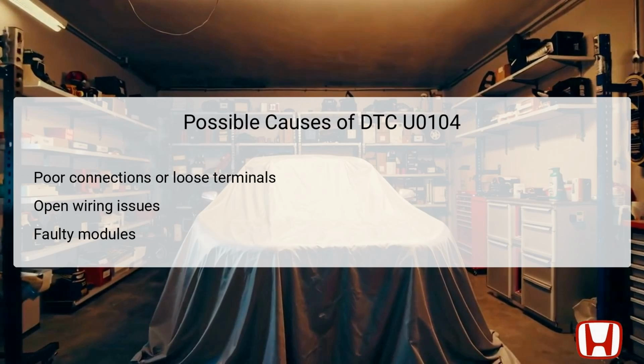There are several potential causes for the DTC U0104. First, poor connections or loose terminals can disrupt communication between the modules. This suggests a need to visually inspect all connections related to the ACC system thoroughly.